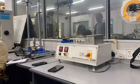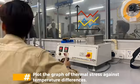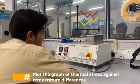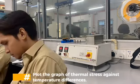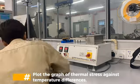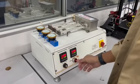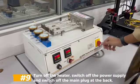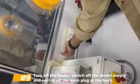After we get the complete set of results from this experiment, we need to plot the graph of thermal stress against temperature differences. The more details about the expected result from this experiment and how to plot the graph, the next group members will teach about it. Lastly, when everything is done, we need to turn off the heater, switch off the power supply, and switch off the main plug at the back.